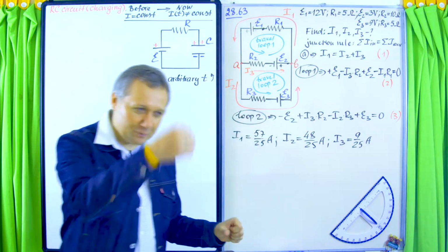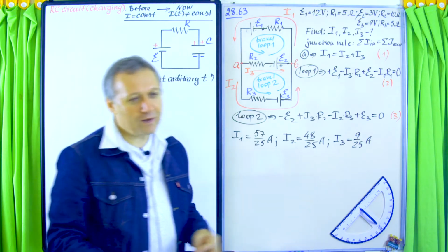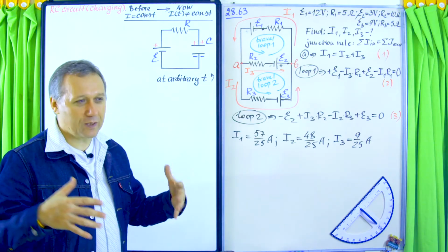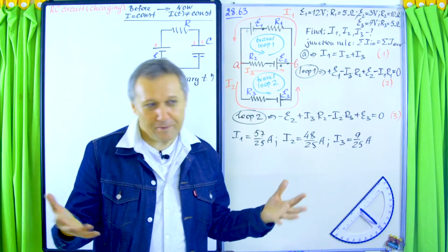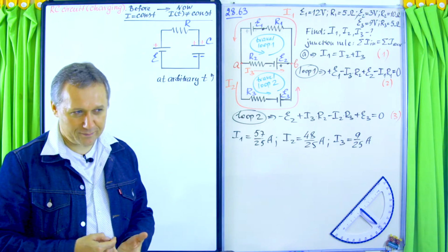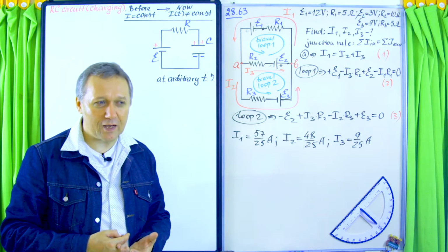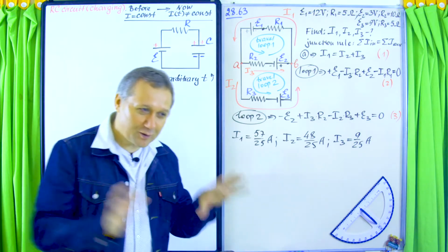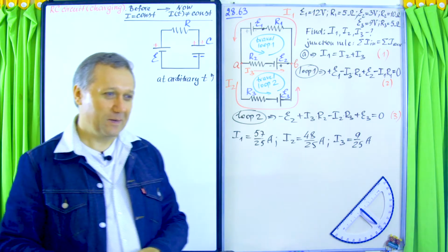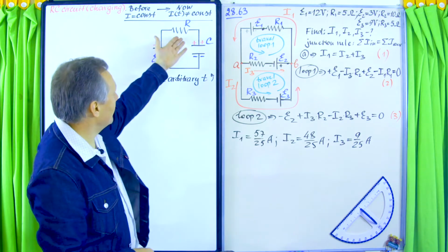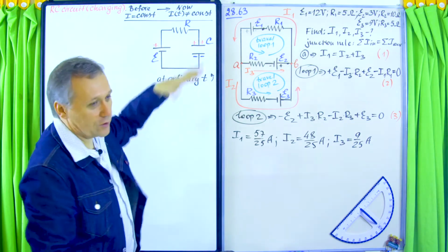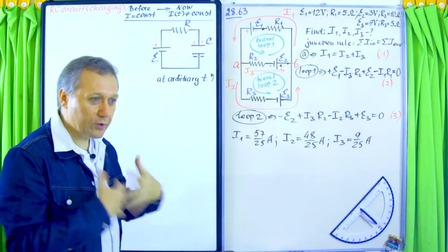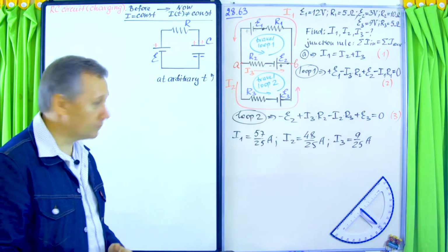It's better to put in a resistor so that current will have finite values and you're not going to damage your system. That's why the resistor is all the time in the system, to slow things down so that you wouldn't destroy it. And the same in the charging case, usually people put a resistor to slow things down.